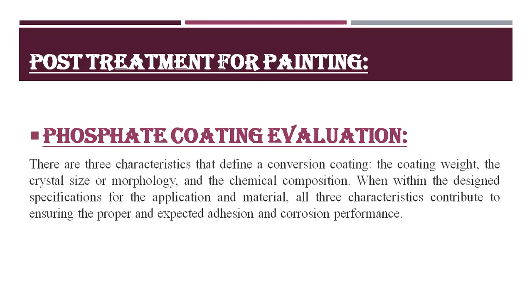Phosphate coating evaluation. There are three characteristics that define a conversion coating: coating weight, crystal size or morphology, and the chemical composition. When within the design specifications for application and material, all three characteristics contribute to ensuring the proper and expected adhesion and corrosion performance.